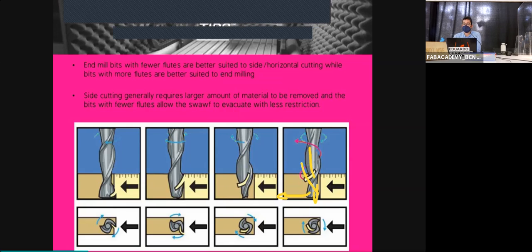So a down cutter always needs to cut in a line. That's why we cannot cut vertically, because the material cannot escape if there is no space on the back of the end mill. Okay, I will repeat that. Yes, it's important. So this end mill is taking the chip, as this color is not good, let's go with green, and pushing it up, no? Imagine that the tool geometry is the opposite, that it is rotating like this. So when you cut, this piece is being pushed down. There is no space. So based on the rotation, it goes on the back, on the leftover space behind the end mill. It's pushing down and back, because the down cutter can only move on the side, cannot do just vertical plunges.